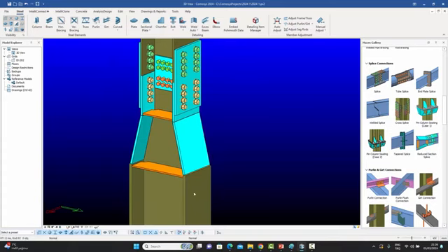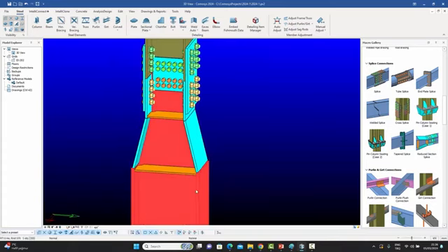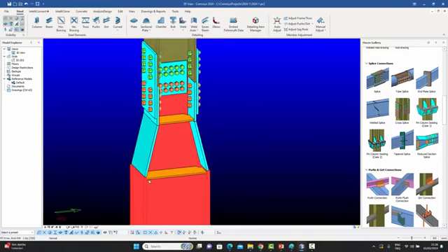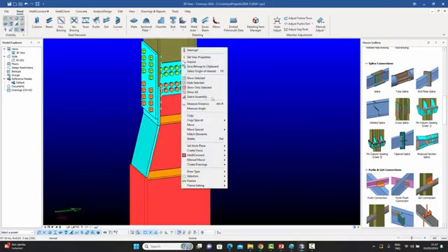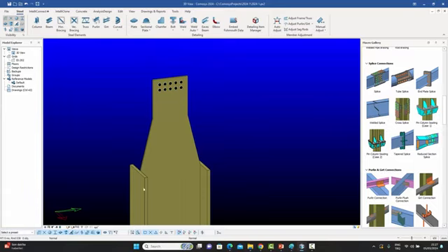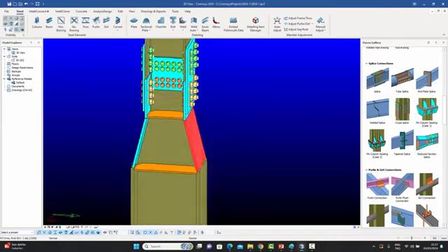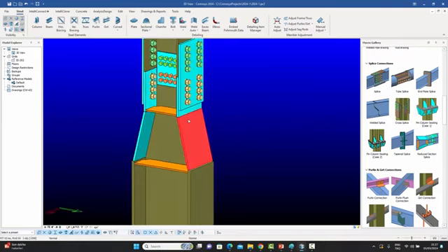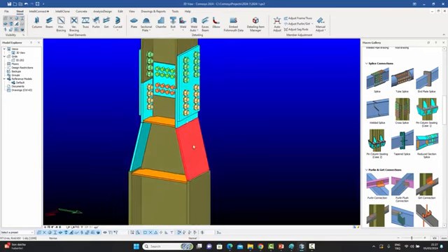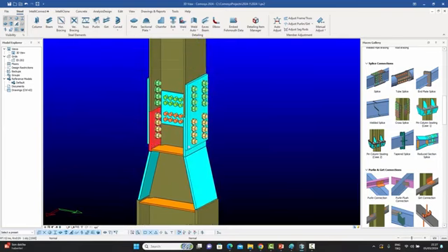Now, as you can see, what it has done is it's taken the first profile, and removed the flanges. Let me just show this one only. So it has taken the first profile, it's cut out the web, removed the flanges completely. I'm going to turn it back on now, and it's used extra plates on the side. So you have the continuation of the flanges in a different way. These are artificial flanges for the bottom column, and then it's continued that with other plates. And now at this point, it has created a normal splice between this one and the other one.